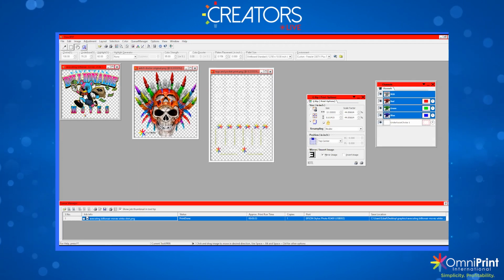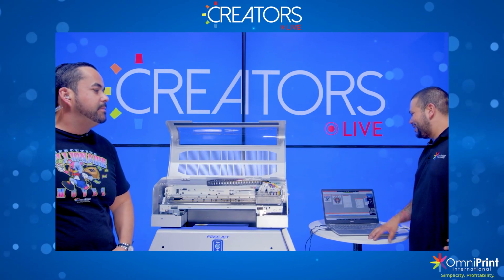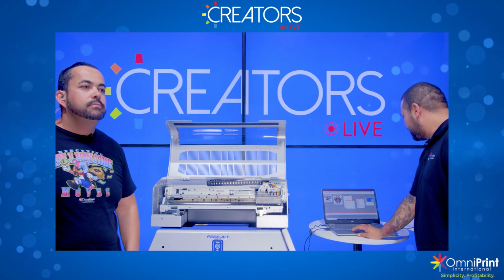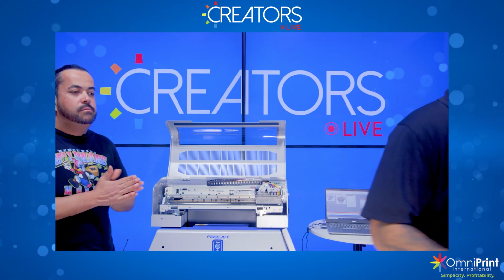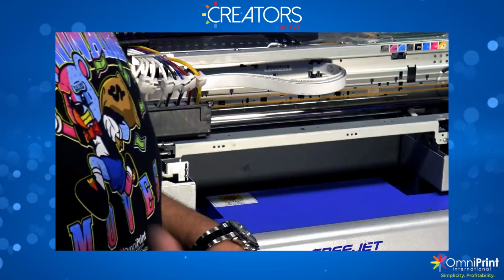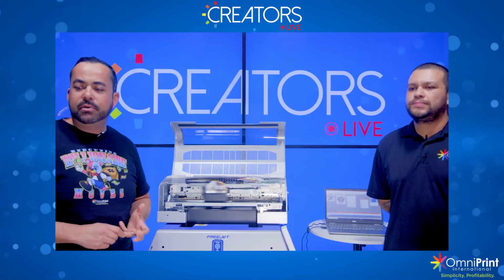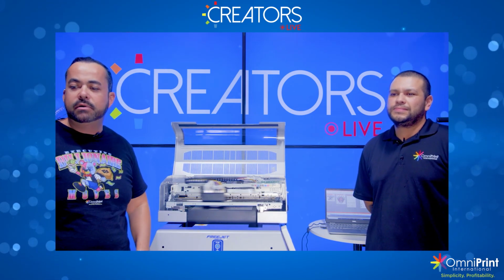So very easy. Like Vic said, we spent the time to dial these settings in. I spent a lot of time dialing this in, with a lot of different films and different powders. We just found everything that works best for our ink and for our printer here. So I'm going to send print and let that get started. One thing to note, guys, is that you're printing the image in reverse. That's why you have to mirror. You're printing your color in reverse and then the white on top of that. That's pretty much the settings that you have to do in the RIP. Everything else is done for you.